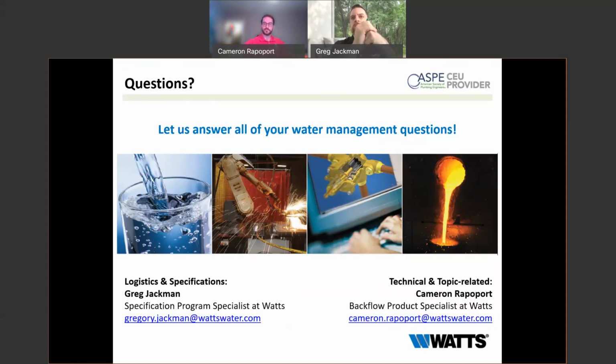Okay, another question here. Backflow before or after a fire pump? The fire pump valves, etc., are not NSF. How is it acceptable to install backflow downstream of fire pumps and still meet code? Typically, backflow preventers are on the suction side to protect the city water mains. It's usually not acceptable. So that's a great point.